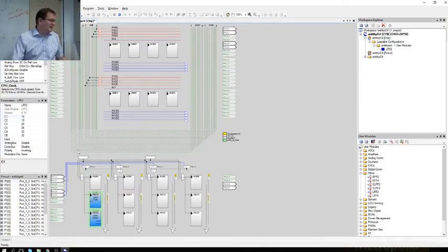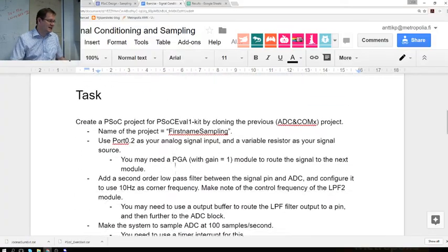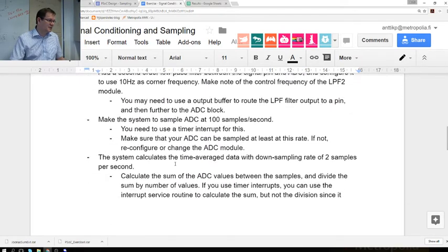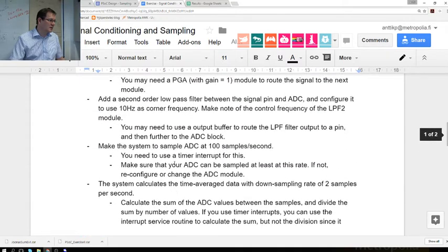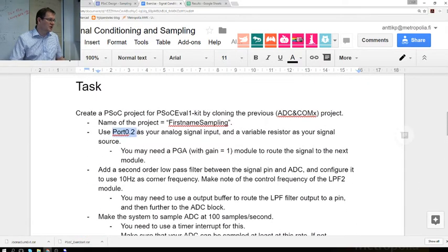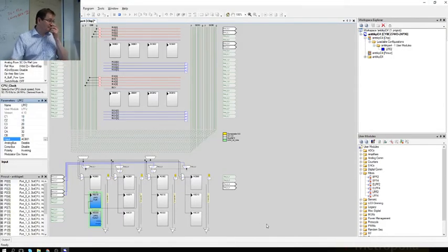All right. Okay, and then we need the signal input. Let's just take it, well, just for fun, I'll just take it from there and add the amplifier later. This is your part of design. Get a routing of the signal done correctly, so that on exercise I'm asking this input signal to come in from where? Okay, use port 0.2. Yep, for analog signal.